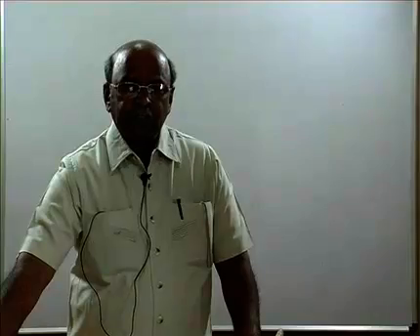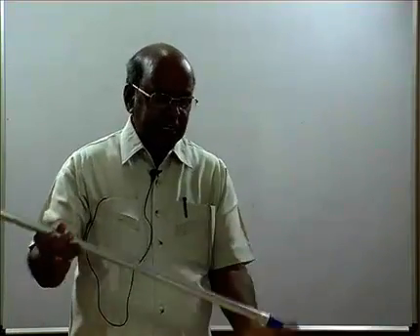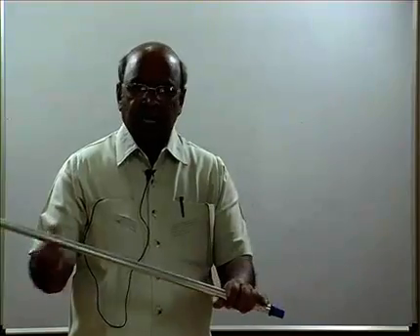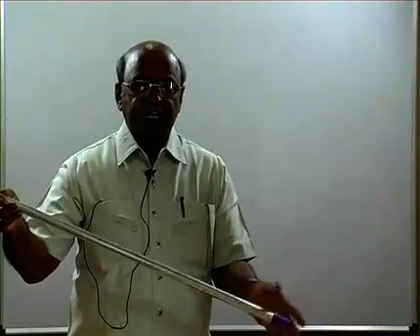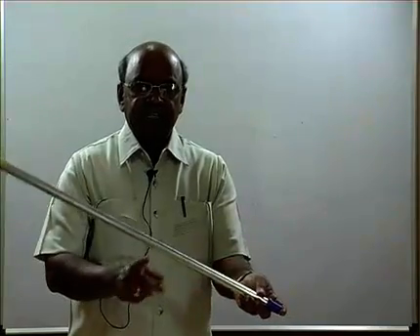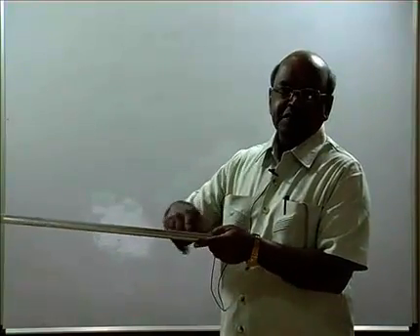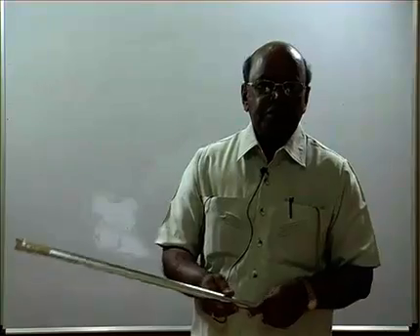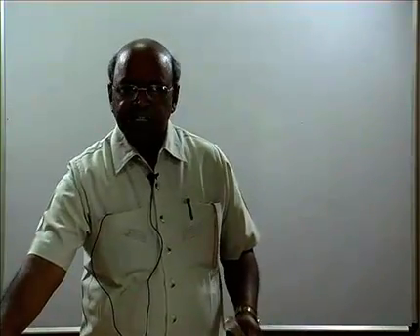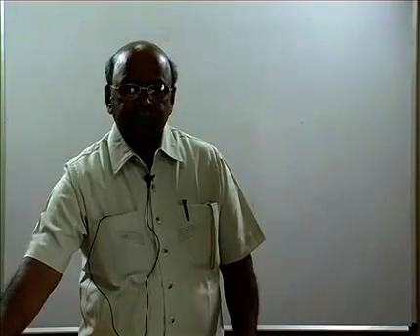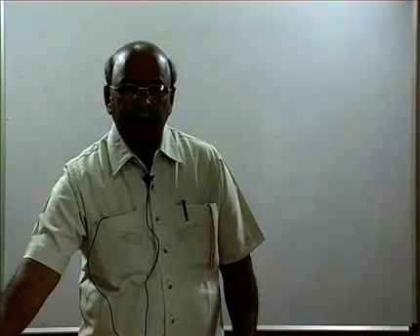so these are some of the problems, direct problems, and indirect problems. What is meant by an indirect problem? Instead of giving the angles, he will say one end is at, say, 10 mm, the other end is at 30 mm. So if they are at different heights, it is making an angle with the HP. Similarly, if it is at different distances from the VP, that means it is making an angle with the VP. So indirectly, by giving the distances, the angles may be given. So these are some of the problems we can go through. Okay, thank you.